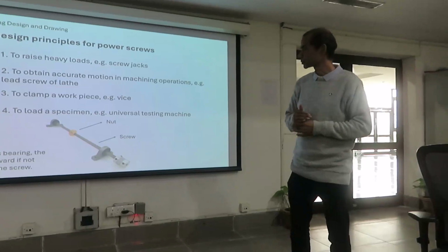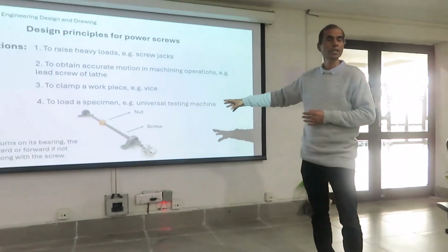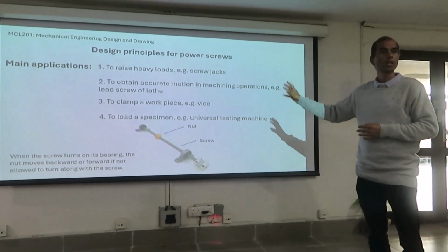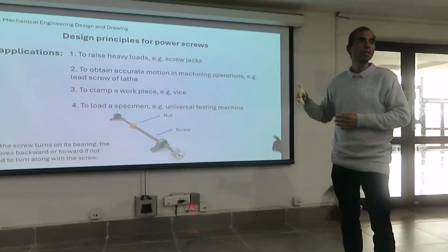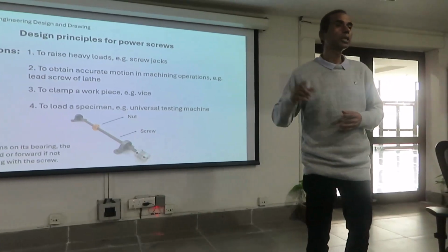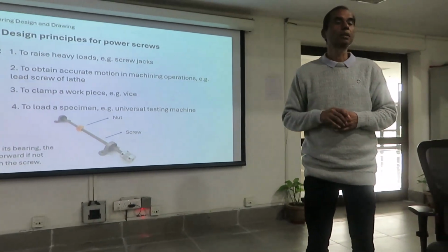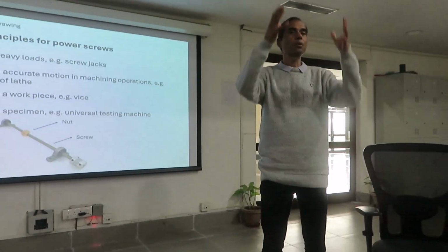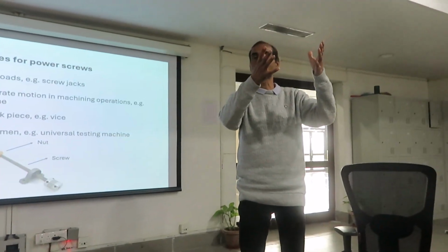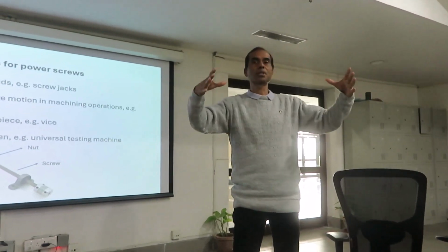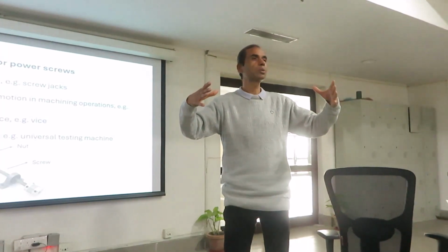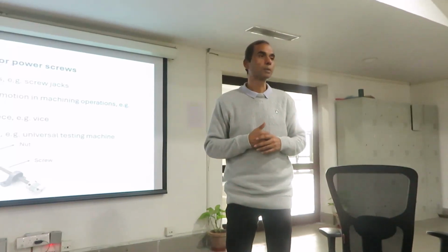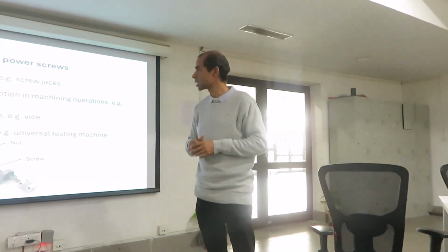Okay, so that's why we will do this exercise of designing this screw for whatever load it has to take. Again, as I said, you should not over design it. You should not select dimensions which will take this load anyway. If I have got 5 kg to be held like this, I will just make this beam so thick that it will take care of the 5 kg. But that is wastage of the material and money.